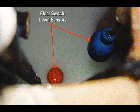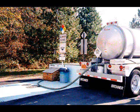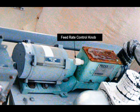Check the suction lines and connections for air leaks or pockets of air and eliminate them. If the pump has an automatic level control system, check it to be sure that the pump turns on and off at the set levels. If water is used to prime the pump, be sure to add the appropriate amount of chemicals to the feed tank. Adjust the chemical feed rate with the control knob when the pump is operating.